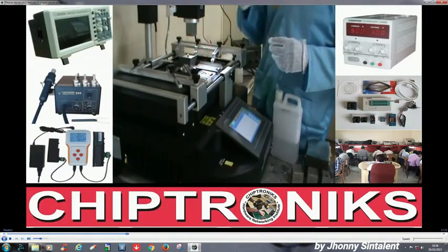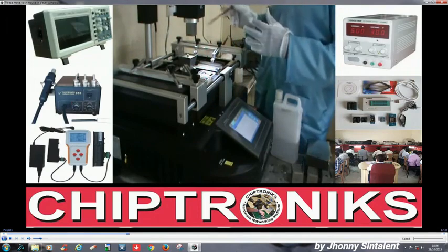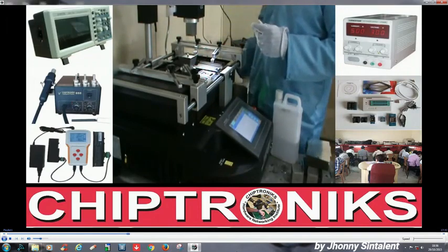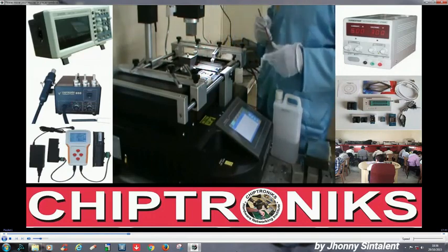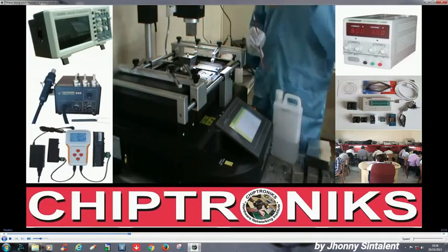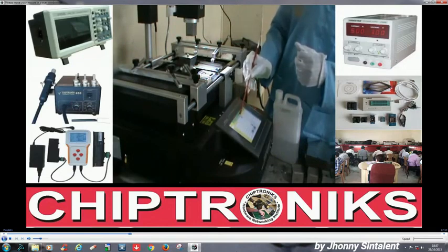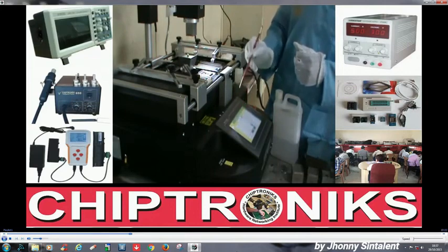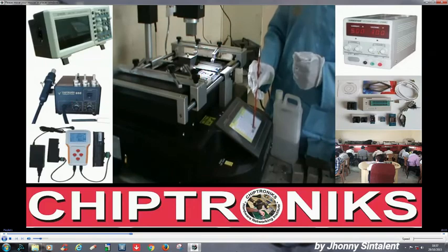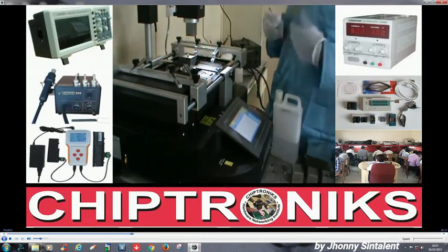And this side heater is not mandatory to use. We can also turn off these side heaters, and it depends on which kind of board we have whether we turn on these side heaters. So now we'll go into the program selection, and you can see in the program selection there is a name. You can go into selection, then there are two inbuilt profiles which we have saved in this machine. Suppose we select PCH, we'll also discuss how to design a new profile, and you just press apply and we can press start, then this machine will be started.